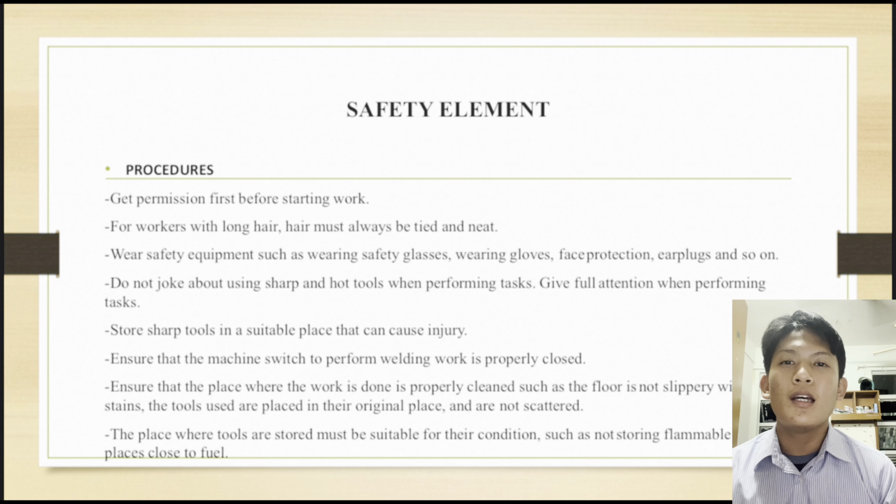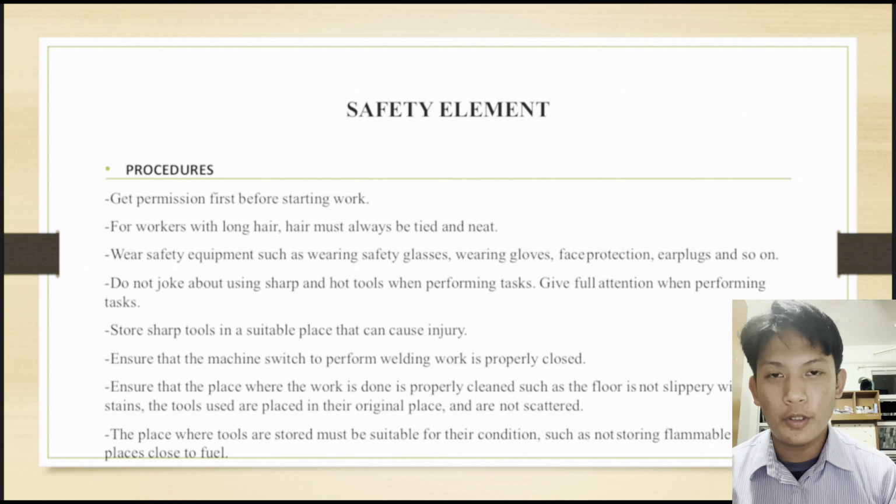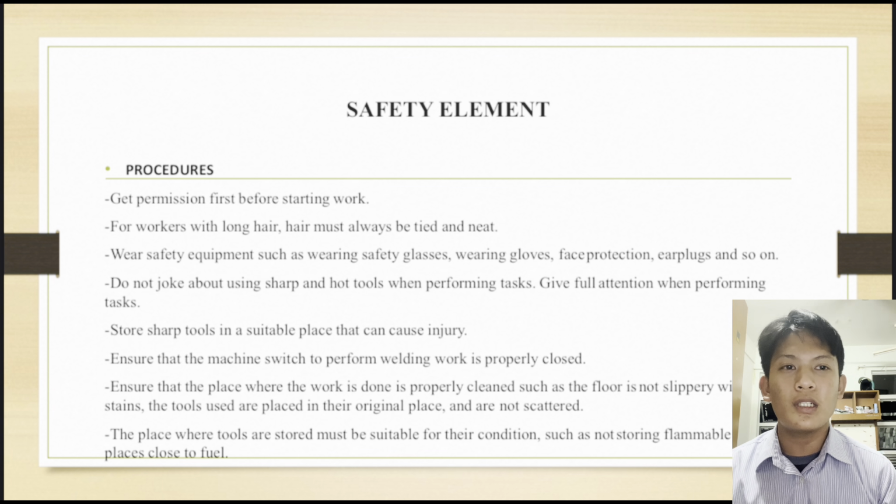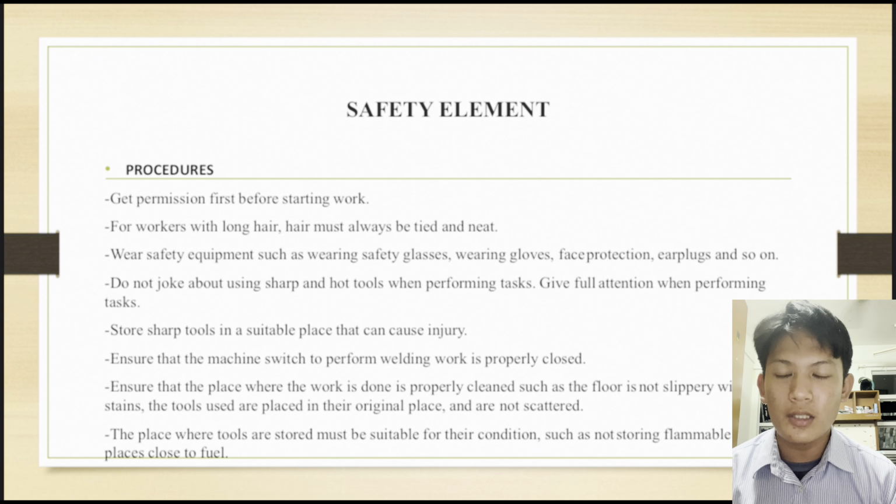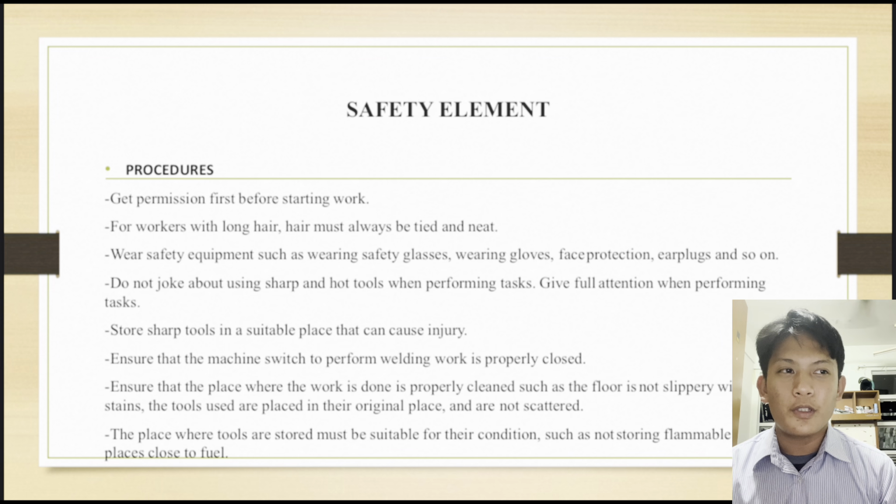Procedures. First, get permission before starting work. Second, workers with long hair must always keep it tight and neat. Wear safety equipment such as safety glasses, gloves, face protection, earplugs, and so on. Do not joke about using sharp and hot tools when performing tasks. Give full attention when performing tasks. Next, store sharp tools in a suitable place, as they can cause injury.